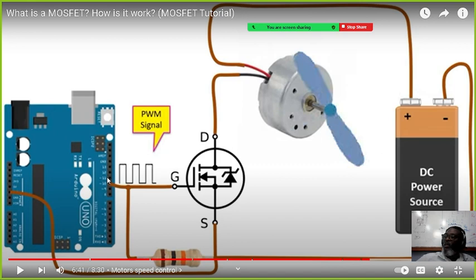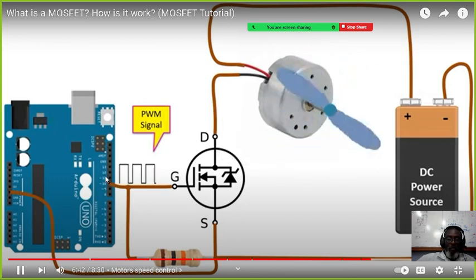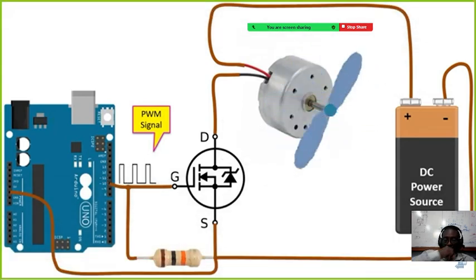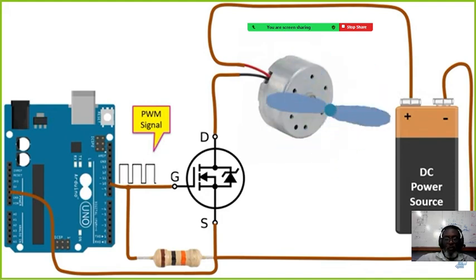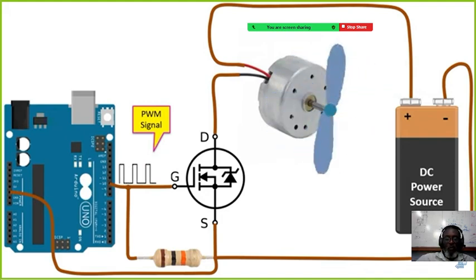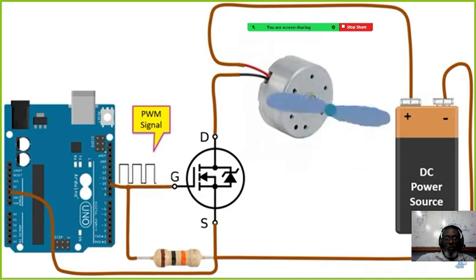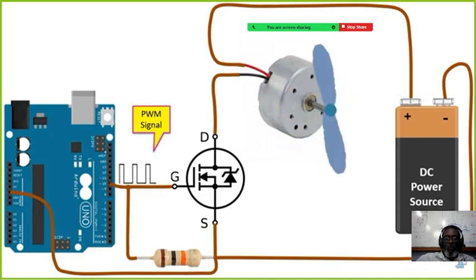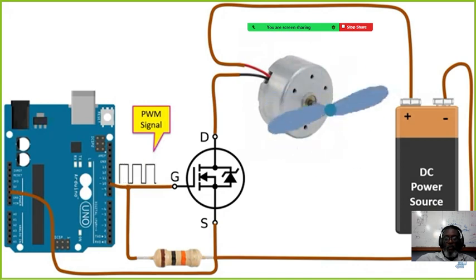We still have a few circuits right here that we use. The resistance value on the gate pin of the MOSFET transistors is very large. There is no current flow. That is, the trigger part and the part connected to the load are isolated from each other. As such, MOSFET can be easily used with a microcontroller such as Arduino.